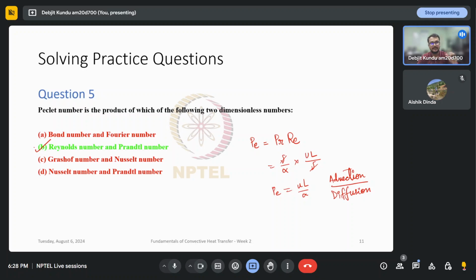So if the Peclet number is very high in some case, then it's the advection, or the bulk motion of the fluid which carries some quantity of interest, that is dominating over the diffusion of that quantity, which happens slowly. Whereas in low Peclet number cases, it's the diffusion that is the dominating phenomenon that's going on. So in that way, the Peclet number is a very important quantity. Okay. Any questions on this? If not, we will keep rolling.